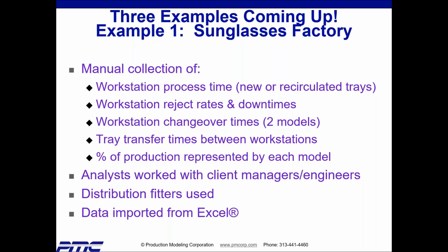What about the third one, the changeover times? If I just made model A and now I'm going to make model B, I might have to adjust my workstation, like resetting gauges, for example. That takes time. If I make long runs of model A and then long runs of model B, I'll spend less time on changeover. But I'll have greater danger of a huge inventory of model A and a stock out of model B. There's a sweet spot in there.